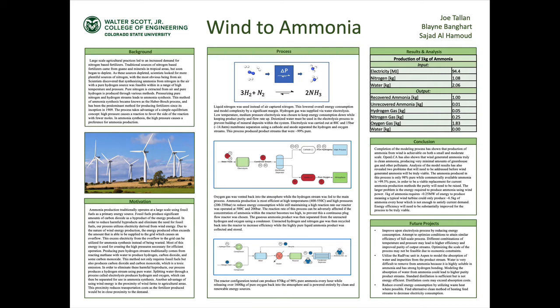So 500 degrees Celsius and 200 bar would produce an optimum range for our reaction that would drive it towards our ammonia production. After the reactants had been heated up, they would enter the reactor at a high pressure and high temperature in order to form ammonia.